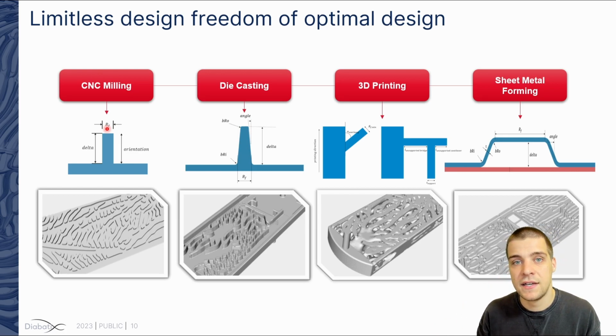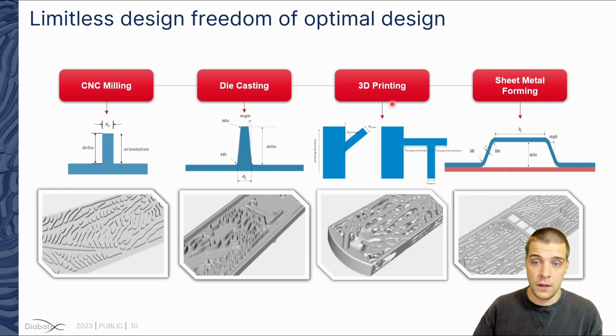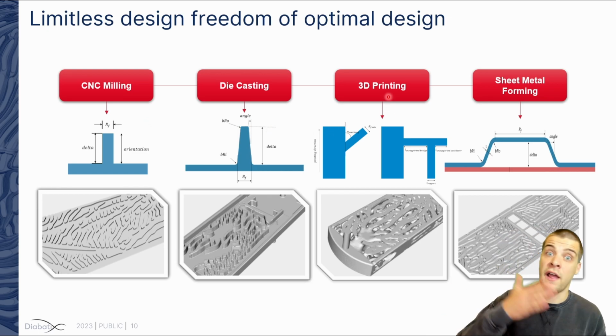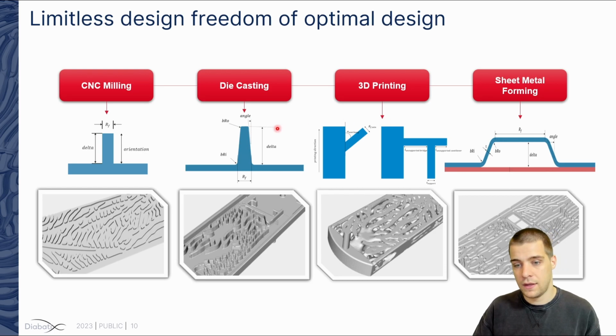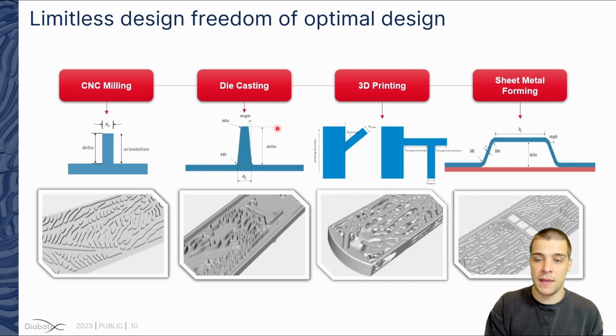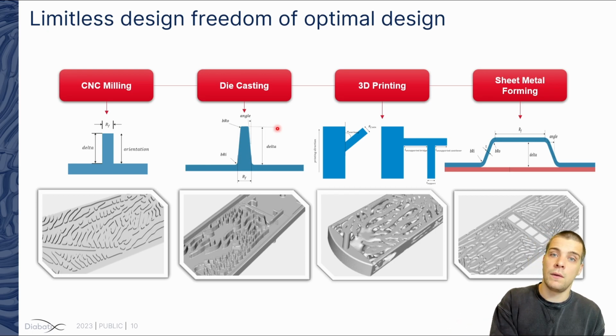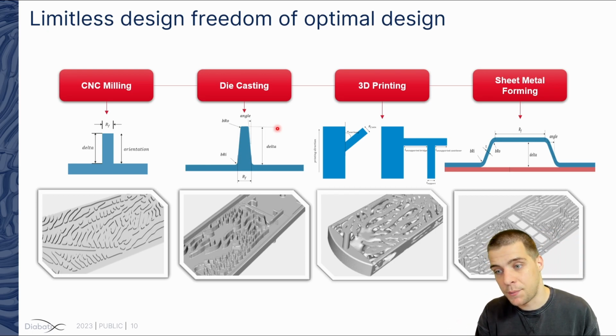Basically, that dictates the minimal channel width. With 3D printing, you have control over the printing resolution of your machine, the overhang angle that your machine supports, as well as the unsupported lengths, both cantilever and bridge. So you can fine-tune those settings to meet your specific capabilities. So whatever Coldstream will output will meet those capabilities.